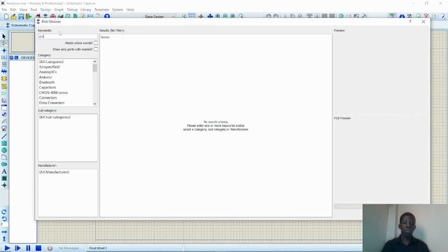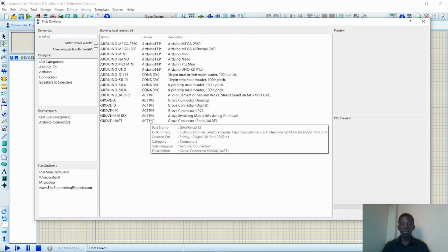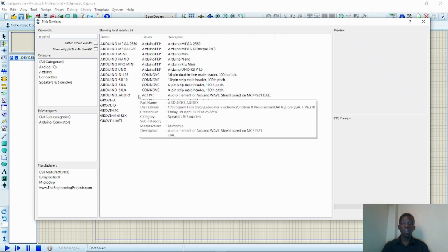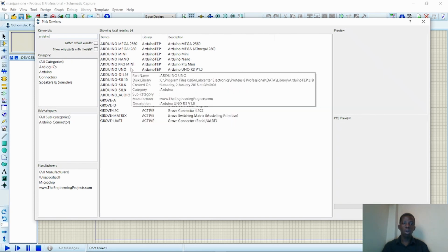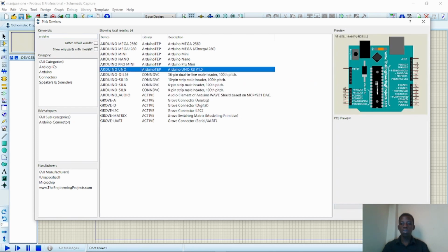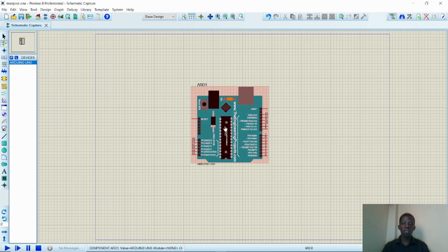I'm going to search for Arduino. If you do not have this showing, it means that you do not have the Arduino library installed inside your Proteus software. For that, I have another video. You can follow up on that video. It will be in the description, and follow up and come back later to this. For those of you who have it, you can come to Arduino Uno, click on Arduino Uno, then left click to drop.